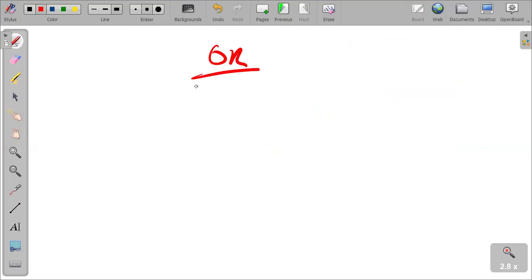And there's a quicker way of doing it, which marks option 2. We would have used each power, P1, P2, to calculate IL1, IL2, IL3. How? We know that power is equal to root 3 VL IL cos phi.